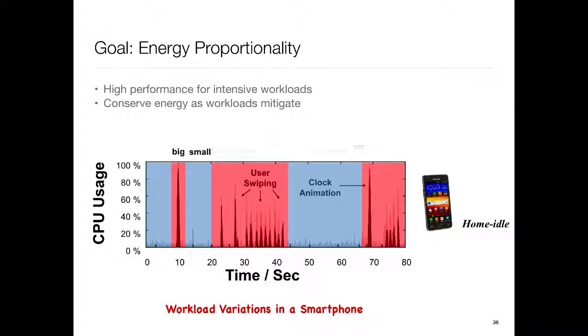So this concept of making a chip with multiple cores, but a diversity of cores tuned for different points in the power performance space, and then letting the software carry the burden of activating the right set at any given time. This raises a lot of other challenges also, like for example, where should my interrupts go? Normally the task is simple: interrupt comes, I send it to the processor. Now you have to send it to the processor which is currently active. So there are a lot of IO related issues that come up here.